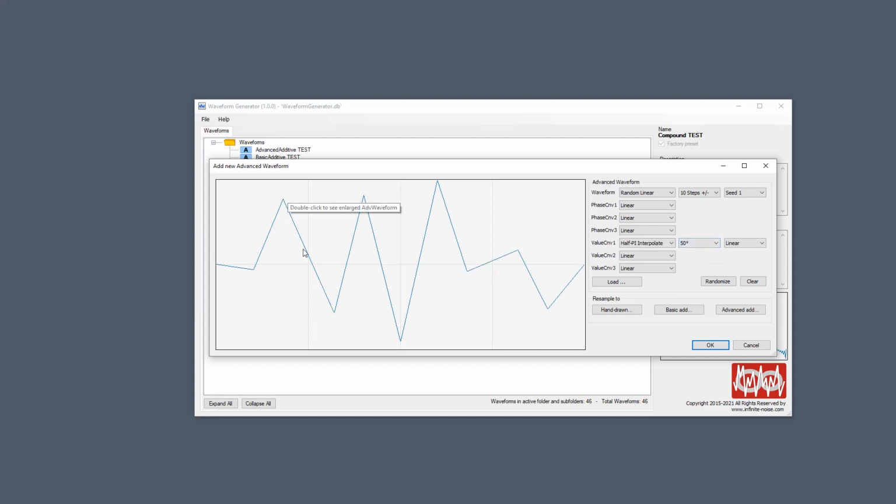So right now, from this point to this point, it throws away the data that's in the waveform, and likewise from here to this point, between these 2 points, it will also throw away the actual waveform. And then in this case linear, it will simply add a straight line between those 2 points, and you can set it up to do an S-curve instead. So you can get these results like this. In some cases you might want to use them because you have something strange going on in the way the 2 parts are connected.